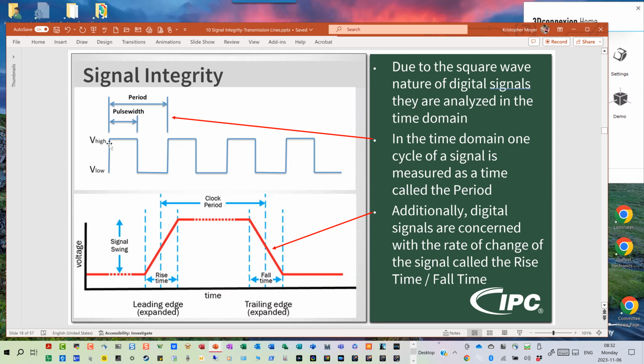So again, it's this edge rate, regardless of clock frequency, it is the edge rate, this rise time, fall time, the more that my chip is going to produce this, right? And this edge rate, even if I have a slow clock going into the chip, if the output driver pin of that chip says, well, I'm going to switch within 200 picoseconds, then I'm going to have that nearly vertical edge rate or rise time, which means I'm going to have this high frequency content in there regardless.